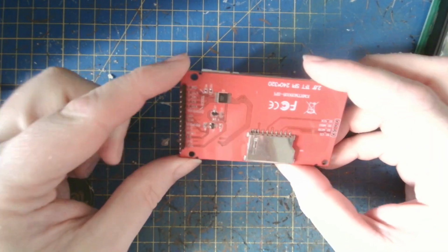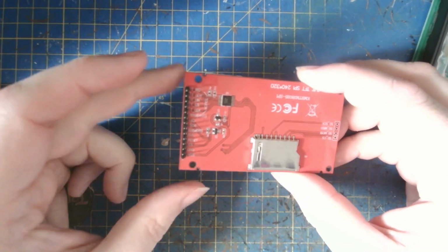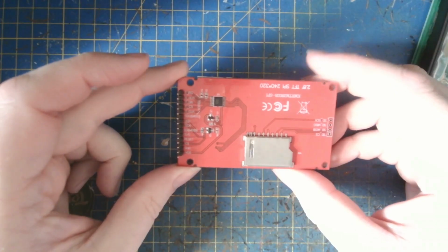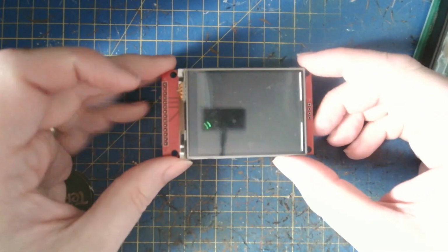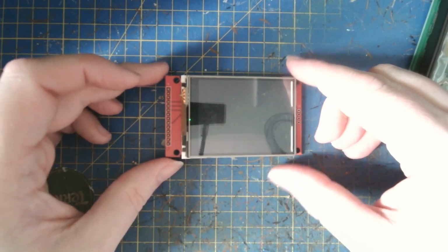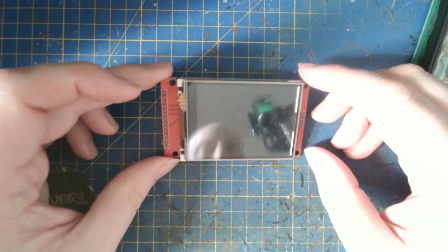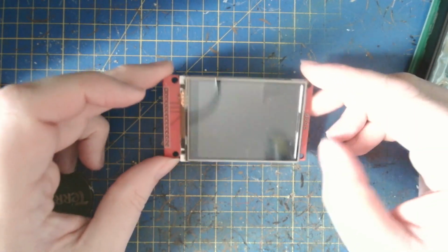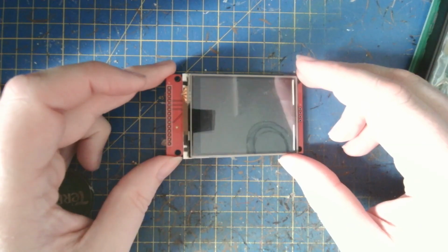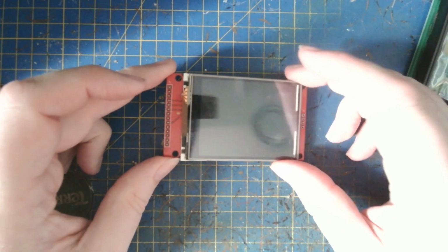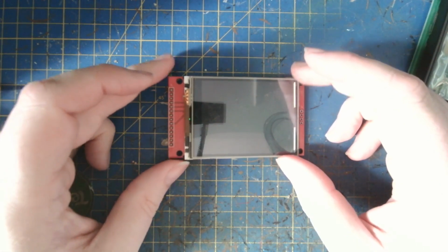This one uses a serial interface, serial peripheral interface called SPI, to move significant quantities of data. We'll have a look at that in a moment. Most microcontrollers can control these. Less powerful ones will struggle to do the more advanced things with it, basically because you keep having to regenerate the display. So if you do one of these with an Arduino Nano or a normal Arduino, you're going to struggle. But if all you want to do is display text, it's not too bad. Just one of the little tricks you can do with it.